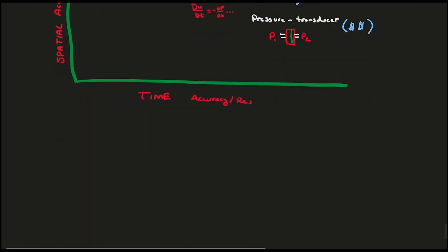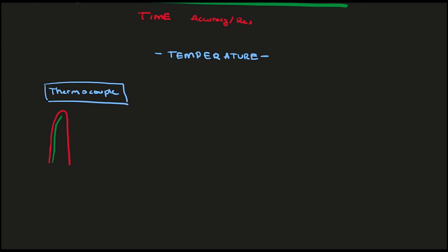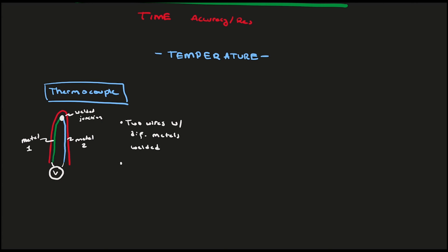Lastly, let's talk about two devices that can measure temperature at a point. First, you have a thermocouple, which are incredibly common in industry. Here, you have a probe with two metal wires of specifically different material that come to a point at a welded junction. These two materials generate a current flow between them, generally very tiny. This current flow is a function of the ambient temperature, so measuring the voltage potential across the two wires can give you the temperature with proper calibration.